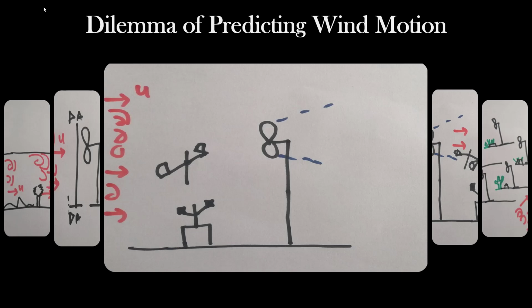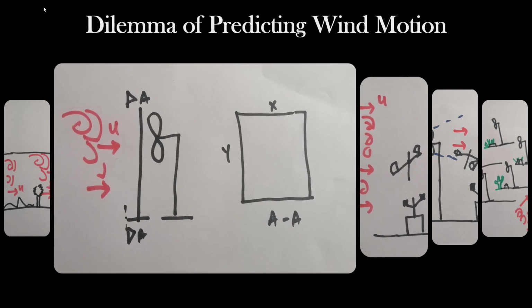The atmospheric boundary layer is within about 1 kilometer or more. After that, you enter into a different layer where probably the wind propagation with the vertical is inverted, so it changes. But within the atmospheric boundary layer, the wind changes according to probably the log law or the power law. But these things vary. When you have a large-scale implementation for a location where you cannot actually install your instrument, then you need to find other methods in order to generate your wind data.